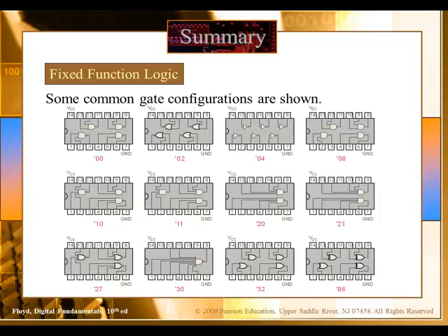We'll give you the data sheet. There are data sheets at the back of the lab manual for each and every IC you'll be using. Now, let's say this is the 7400, the top left one. You will know from here which pin is what. You see what I'm saying? Let's say pin 1 and pin 2 are the inputs, and pin 3 is the output.